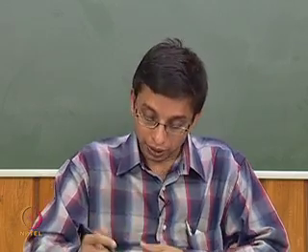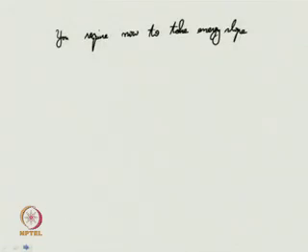However, for such compound sections or flood-causing channels and all, you may need to take into account the total energy at the upstream and the total energy at the downstream. You have to evaluate the energy slope first, then compute the corresponding discharge. So, here you will see that during the flood, when it enters the flood plain, the velocity will be drastically changed along the flood plain.